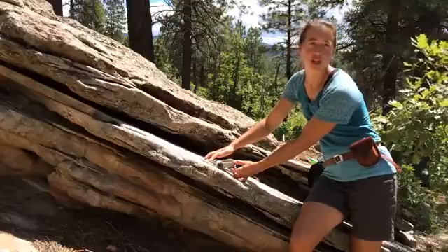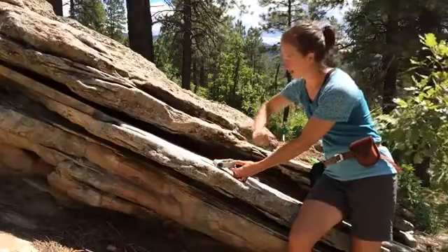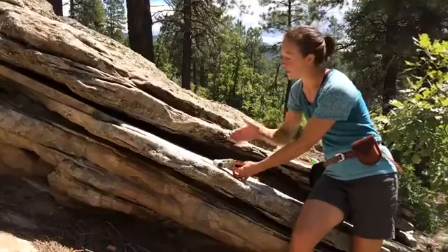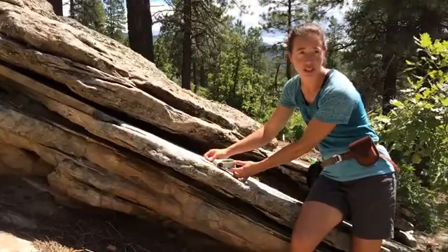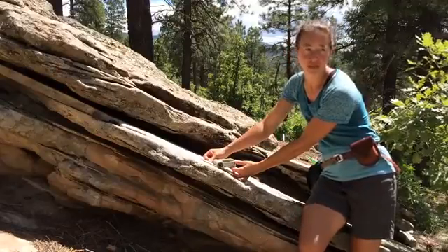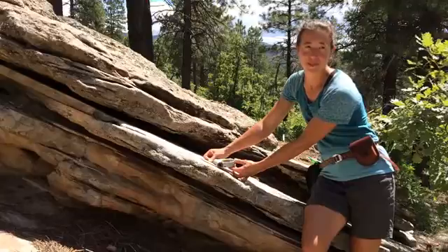Sometimes it will be the general cardinal direction or quadrant pointing away from the hinge. In this case, dip direction is towards me. Sometimes, though, it will be in the opposite direction. There isn't a magic button for this. You have to be able to visualize your measurement plane to properly measure it.